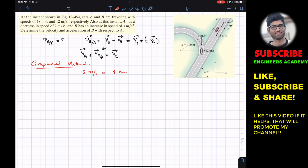Similarly, if the velocity of car A is 18 meters per second, so 18 meters per second is equal to 9 centimeters, and 12 meters per second is equal to 6 centimeters. So now by the head to tail rule, we have to subtract the V_A vector from V_B.